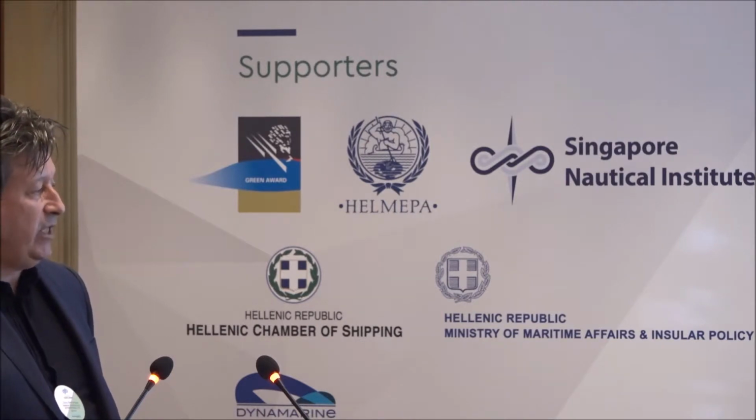So the types of mooring analysis that you can do. Static mooring analysis. Typically that is just wind and current, but can also include wave drift forces and other forces like tugs and bank effect. And that's the sort of common analysis that is specified in OCIMF MEG 3, where they say run a 60-knot wind from all directions with currents at set directions and speeds.